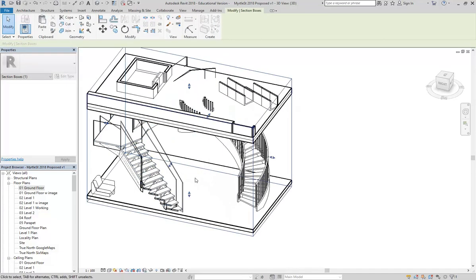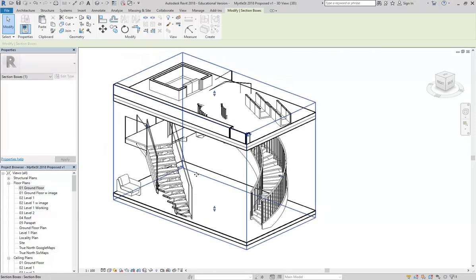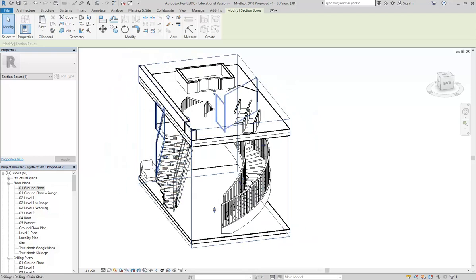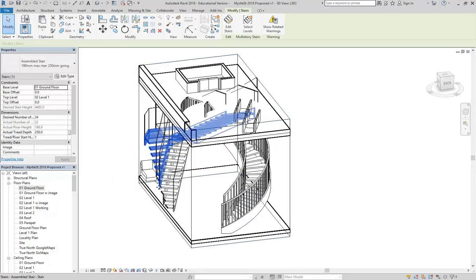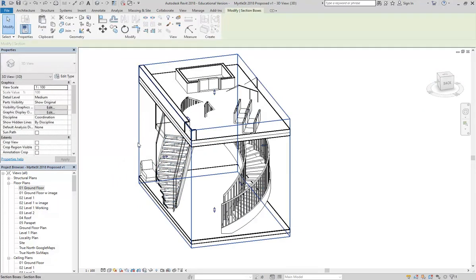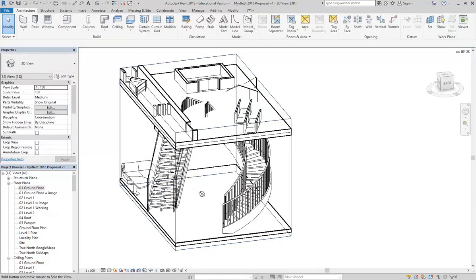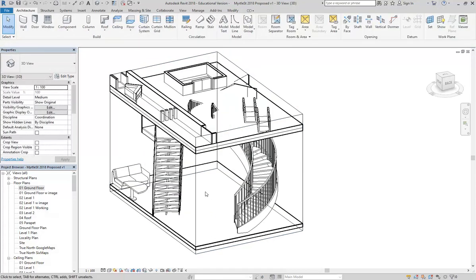In terms of stairs that aren't required, there aren't really defined requirements for things like the width. But for required stairs, there are definite requirements. If it's a 2-level unit, would that be required stairs? No, required stairs go from the unit in and out of the building, to the public space. It's for fire egress, basically. If it's internal, in the unit, do you still have to put that landing here? Oh no, they still have that requirement.